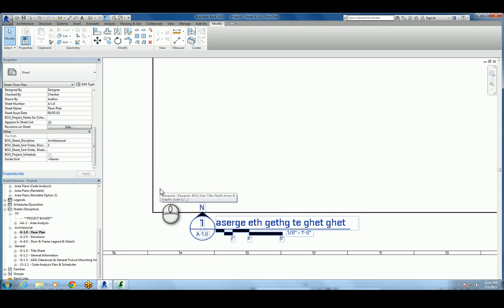Well, for starters, we're required to have the graphic scale there. U of M and other big companies want a graphic scale. That's simple. The reason they want a graphic scale is if you shrink the sheet down, that 1/8 inch no longer applies.